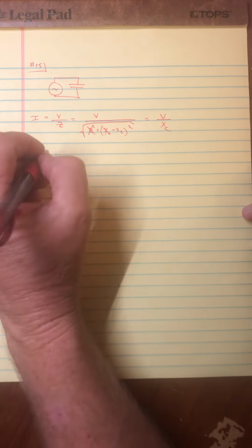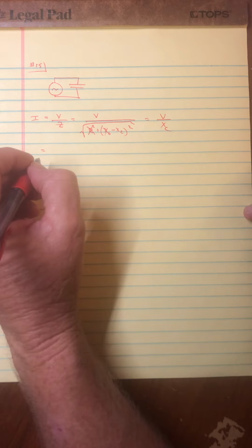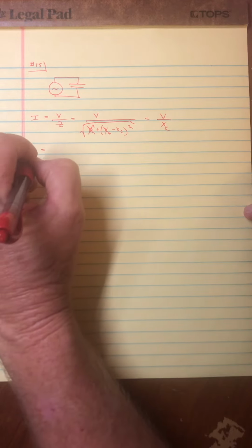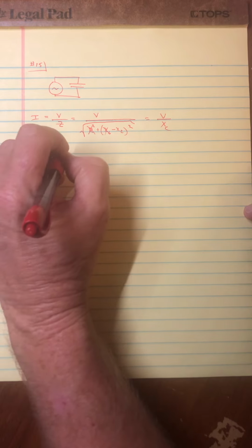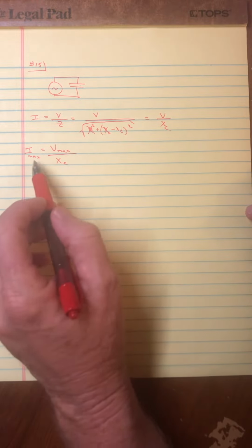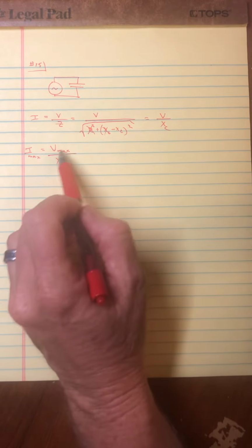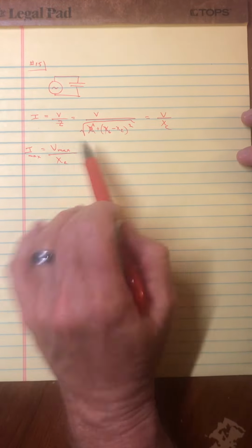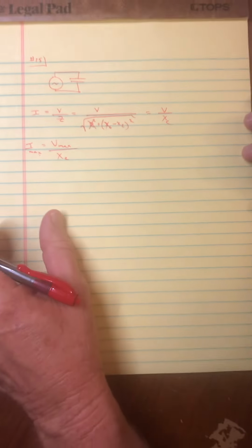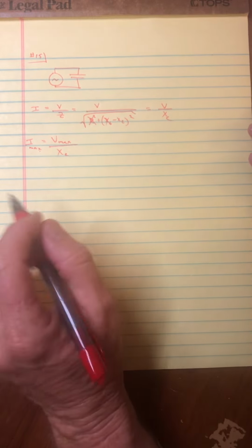And we can then put in, and this is where I'm going to say again, if we're hunting for maximum current, we would put in maximum voltage. If we were hunting for RMS, we would match RMS voltage with RMS current. Or we can find the maximum and then divide by square root of 2. That's how you can get the RMS. So they match there. That's why a lot of times we don't write something down below, because we know it works for RMS as well as maximum.